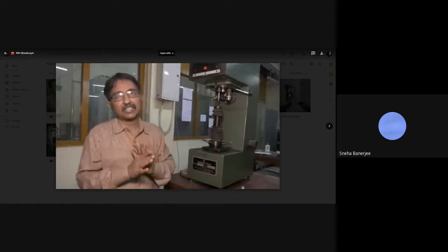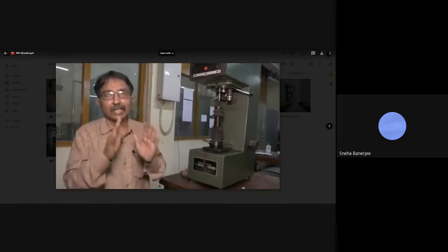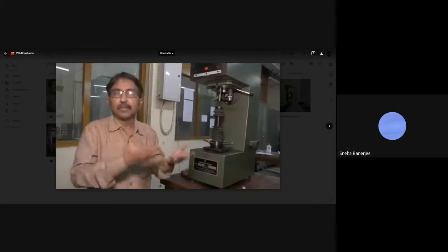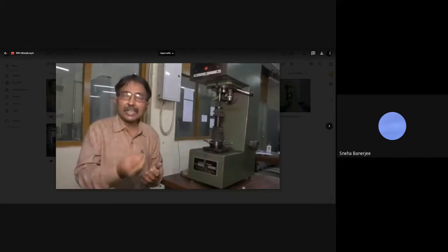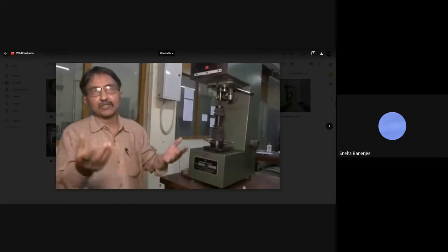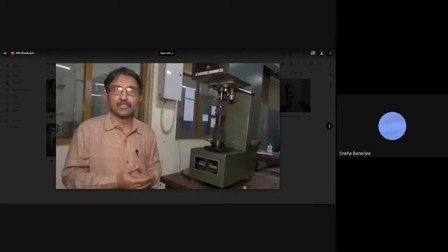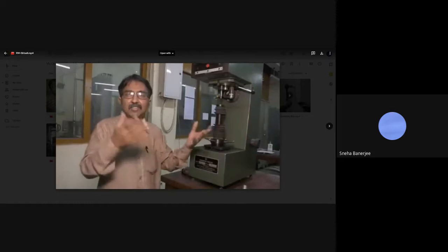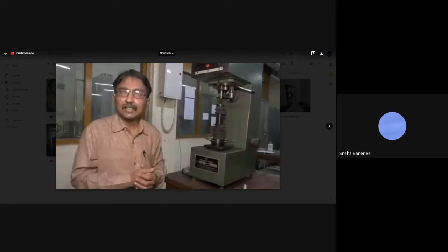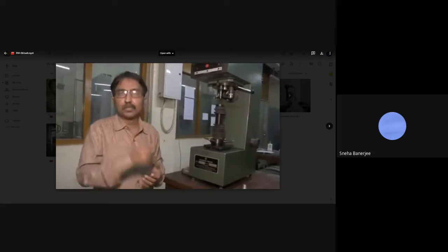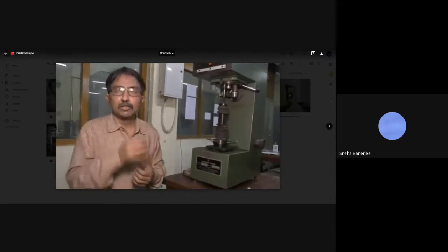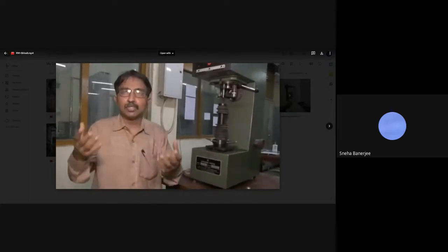Also, it can be expressed in a unit which is the same as the unit of pressure or stress, like GPa or megapascal. For example, in case of steel, we have already measured in Rockwell, it's coming out to be say RC 65 or something like that. In absolute scale, we can call it 2 GPa. So hardness of steel can be 2 GPa.